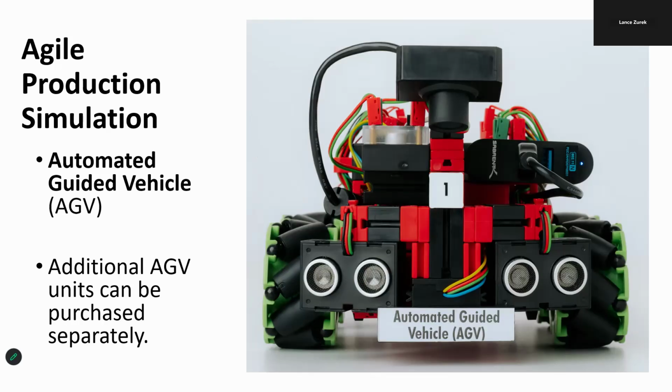The AGV is a track-bound vehicle that follows the printed black lines or tracks, which you've seen on the factory floor in the previous photos. It uses ultrasonic sensors to help it detect obstacles that might be in its pathway. The vehicle itself has omni wheels, which allow it to move in all directions. Two buttons and a photo transistor help the vehicle dock to each factory station.